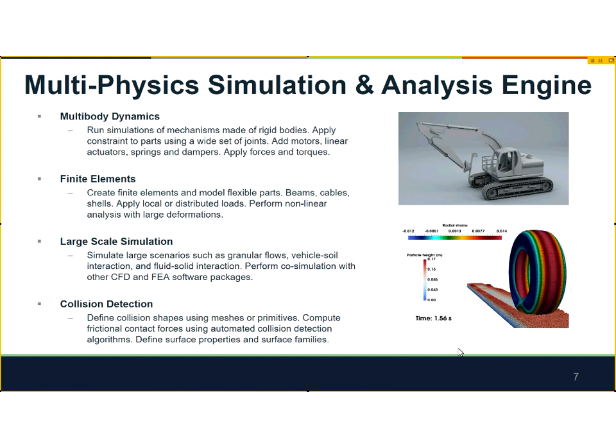Finite elements is another one that we knew from the start that traditional finite element methods were not fast enough to model basically the deformation of a system on this scale in real time. And so we've used a finite element analysis method from this tool that allows us to look at large deformations every time step and capture the expected response to a sufficient fidelity in real time.